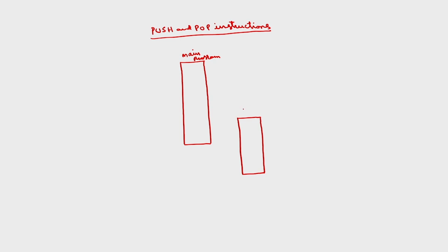Say a multiplication operation is coming several times, I can write a multiplication subroutine, or you can also call it a procedure. While the microprocessor is executing these instructions, suppose somewhere a call instruction is there, call mul.